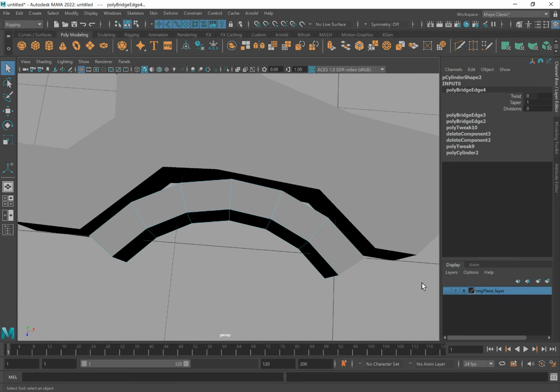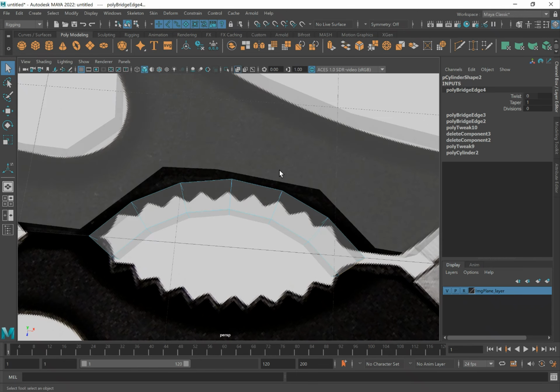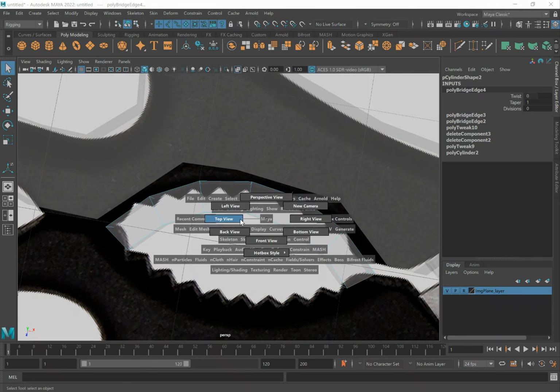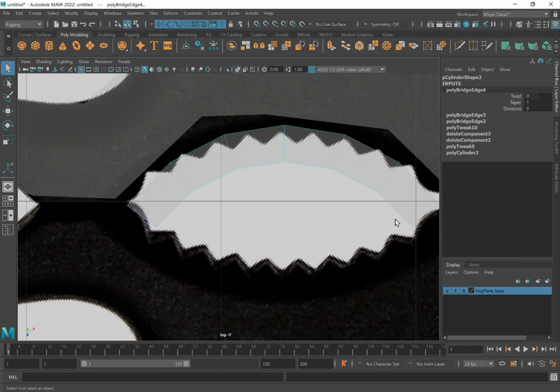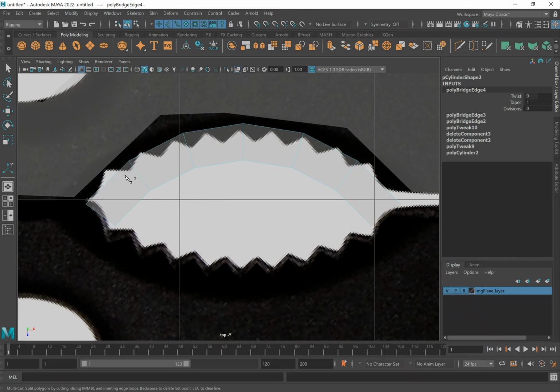From here, I will need to find a little bit more to produce the edges. Looking at over here, like I said, we are not going to be so specific about things, so probably one at each. If I do this multi-cut, hold down shift to get a midpoint, and then hold down control at the same time, I can cut right in the middle. Something along those lines.